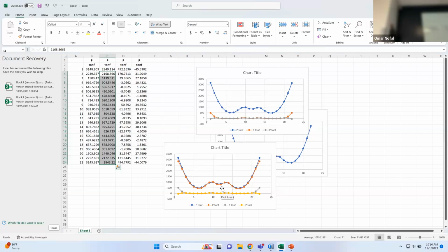Okay, so I'm done with the shear lag on this side. So what I'm looking for, maybe you pick story number one and you get the shear lag at this story and that's it. And you get it for all the 10 models that you have and plot them maybe on the same curve, or if you want to plot them as separate curves and put them together, that's fine. As you can see, it just takes a second. You select the columns, show the tables, get to the Excel, and then plot, copy, or screenshot of the chart and put it in your report.